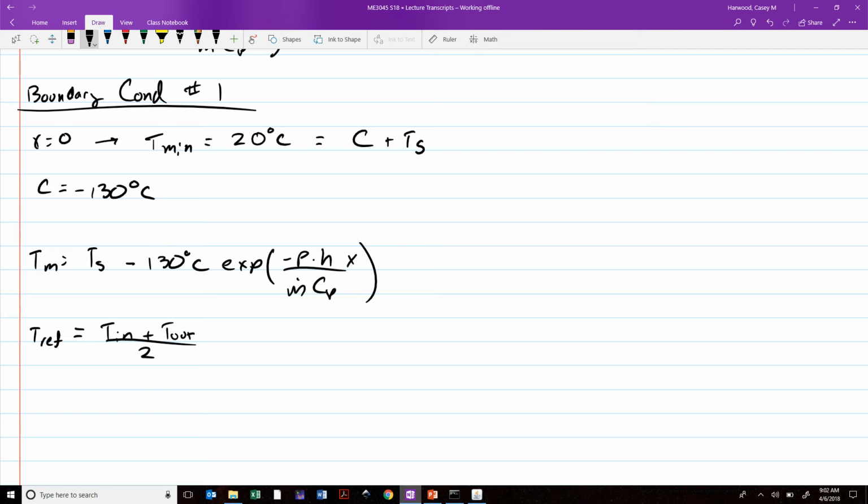What we're going to do is go ahead and first make an initial guess at what T out is. We're going to use that to look up the properties from the back of the book, and we're going to see what kind of T out we calculate with the solution to the problem. If those two things don't match, we're going to need to update our guess and iterate on the solution process until the T out that we guess and use to look up the fluid properties matches the T out that comes out the other end of the problem.